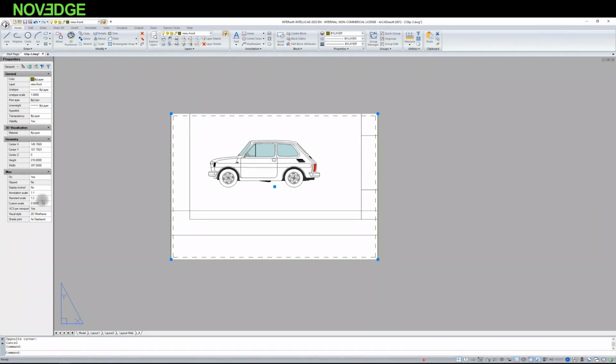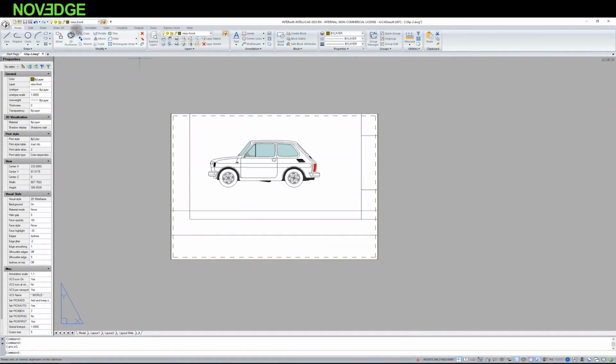I just check every time if I switch to that viewport. I check if the wheel has accidentally shifted backwards or forwards. That would mean that I, of course, changed the scale myself, so we always have to be vigilant about it. But by copying, we can quickly set up the whole drawing. For example, with 5 sections of the drawing, we create 1 sheet, then copy it 5 times, and in each sheet we only change the drawing number, the name of the drawing, and move what is on it for printing. It's a one-time task, and it keeps the project tidy.